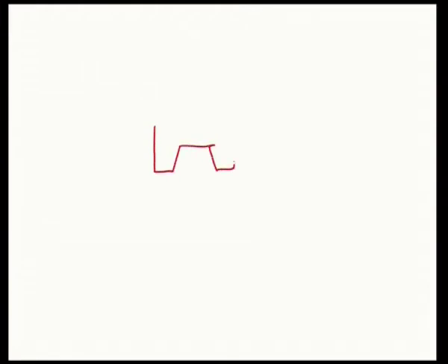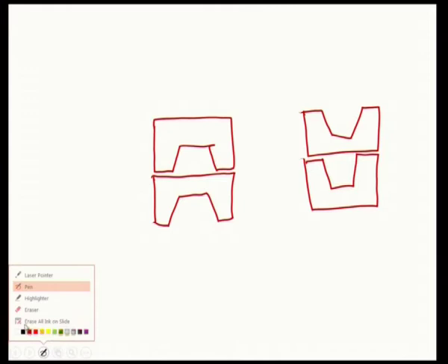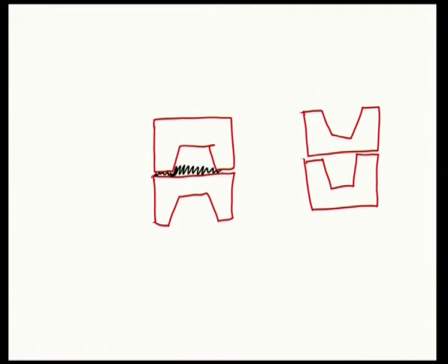So this brick is laid with frog in the bottom. This is one course of brick and this is the next course of brick. And if you have frog on top, this brick is laid with frog on top. Now mortar happens. So this is the mortar in between the bricks, and this is the mortar. Since the frog is on top, the mortar tends to fill the gap between the bricks.